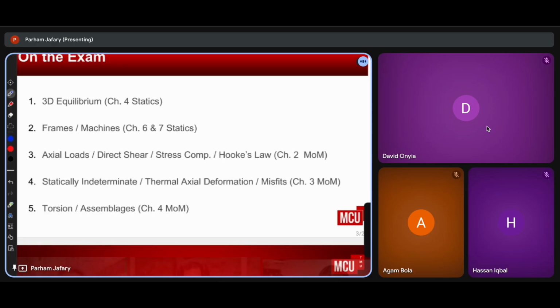So if I connect these two and come up with an axis AD and take the moment around AD, then I won't be needing to worry about all the components of DX, DY, DZ, or AX, AY, AZ. So I have 6 unknowns that I don't need to worry about if I take the moment around AD.